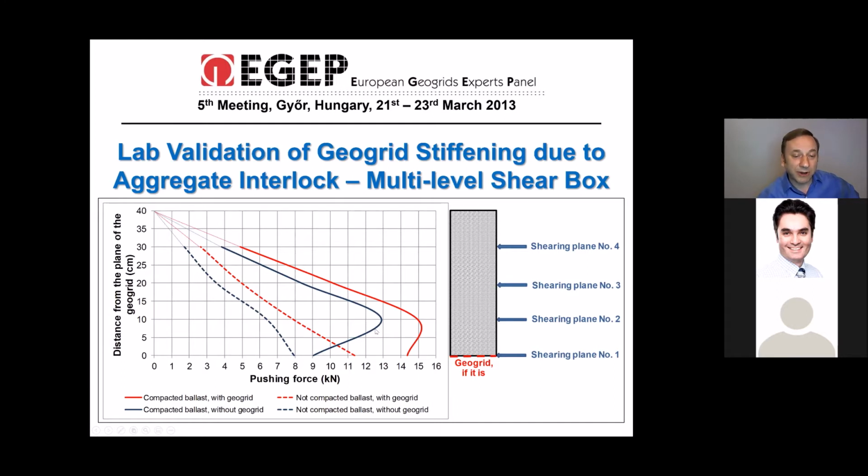But in the case of a well-compacted one, there is an almost 10 centimeter zone above here that is extensively stiffened, with increased modulus or increased forces that will eventually cause a stiffening effect right here in that zone. And that stiffened zone is something we like to understand because that's where everything is stationary, particles aren't moving, and you have an enhanced, stiffened modulus.